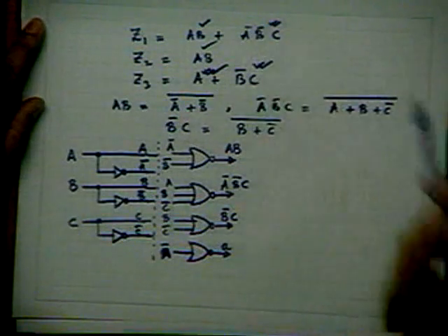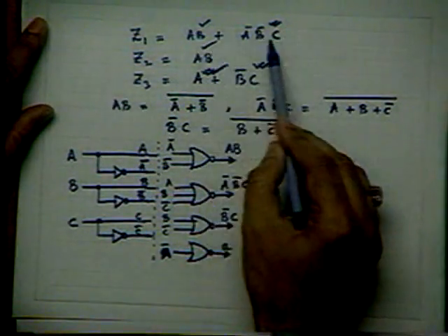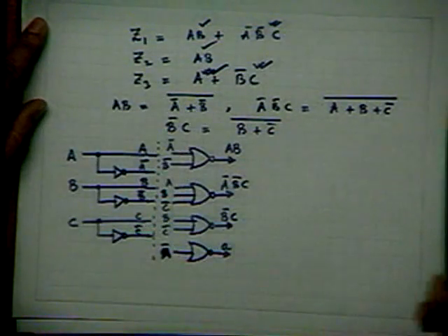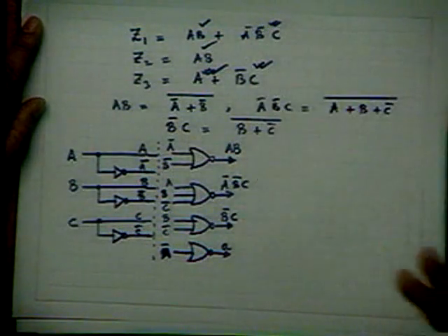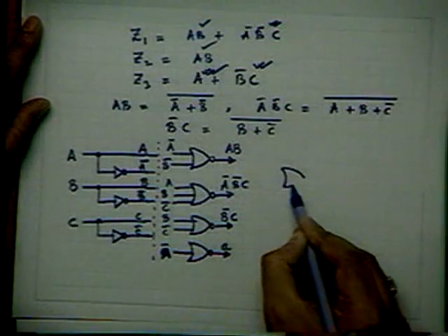These are the product terms. And ultimately, I have to combine them to produce Z1, Z2, Z3. As I told you, NOR is natural, therefore I will first make the NOR functions out of them, and then another inversion stage to produce the final function. NOR, invert is OR. So because there are 3 output functions, I have to take 3 NOR gates.